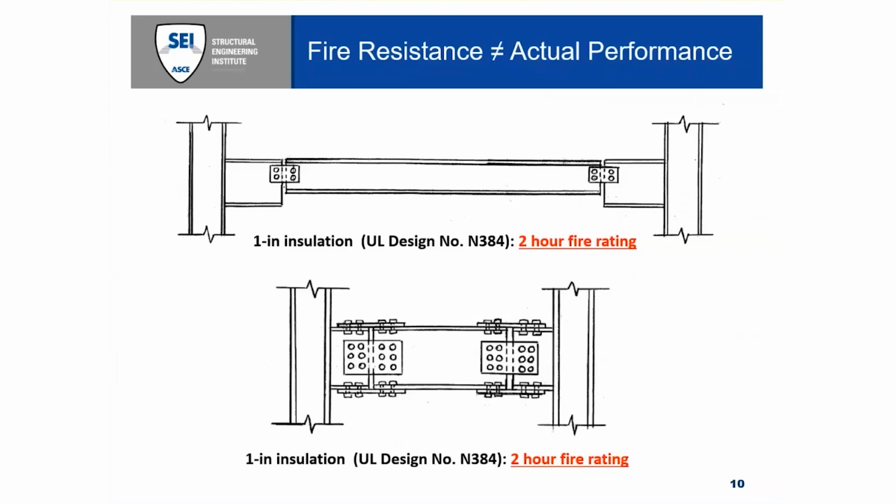But let's look at that second system. It obviously has a higher capacity to endure fire exposure, owing to the fact that it has a very short span and extremely robust connections. However, if 1 inch of fireproofing is applied per this specific UL listing or many other listings of the like, both assemblies would be qualified for the same level of fire resistance.